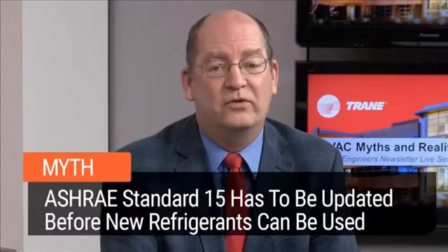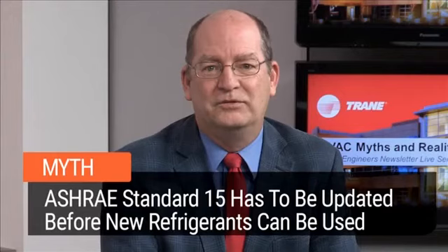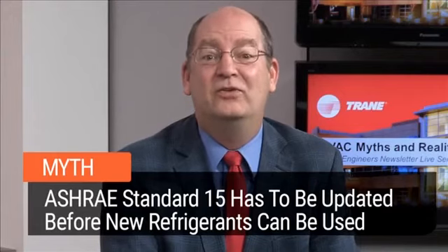The reality is that all refrigerants that have received an RCL and safety classification per Standard 34 can be applied using the requirements of Standard 15. So this myth is busted.